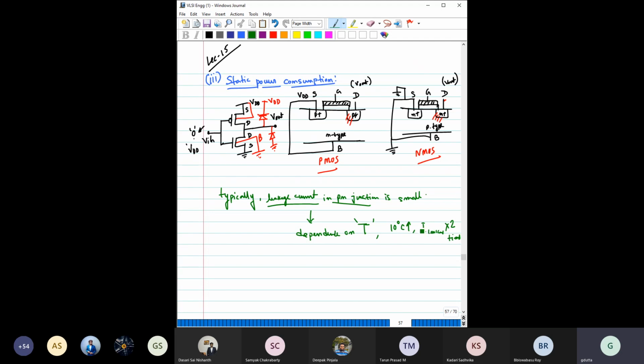And when you are operating a transistor, there will be some power dissipation, and the dissipated power would be radiated as heat, which will raise the device temperature. So the junction temperature would not be at room temperature, but at a higher temperature. If the temperature rises by 60 degrees, then you can imagine how many times you have to multiply to get the leakage current. So at elevated temperature, this leakage current would be an issue, right?